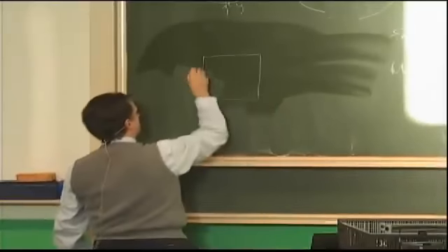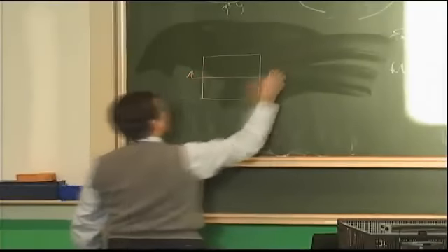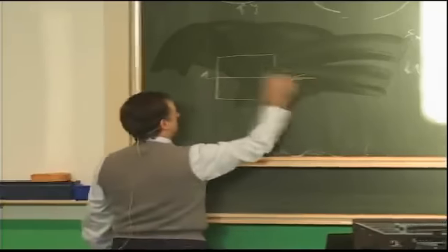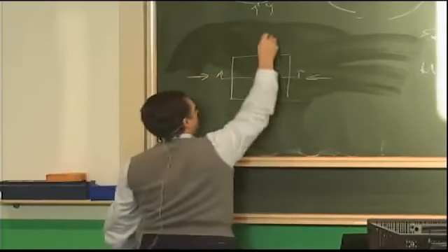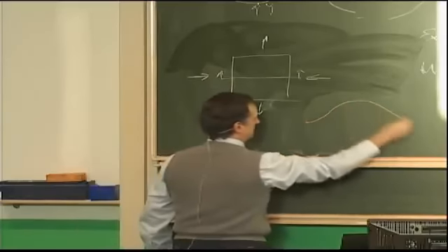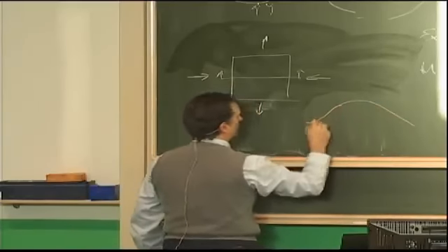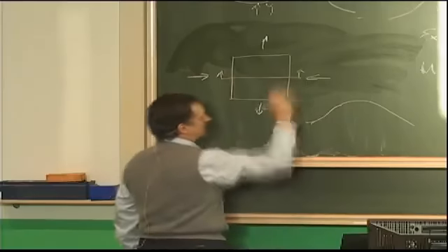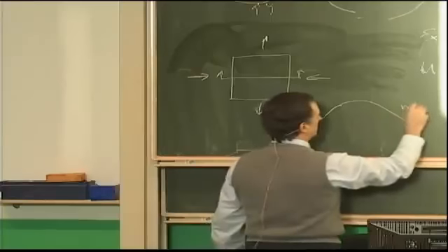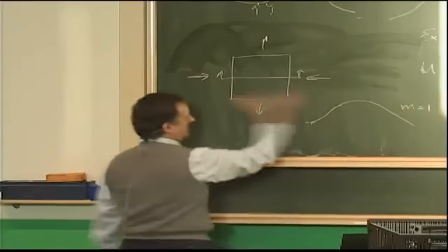If I have a plate and I look at it by making a cut here, let's say under this kind of loading, it looks like this. This is the shape at this location here. I have one half wave, M equals 1, in the X direction.